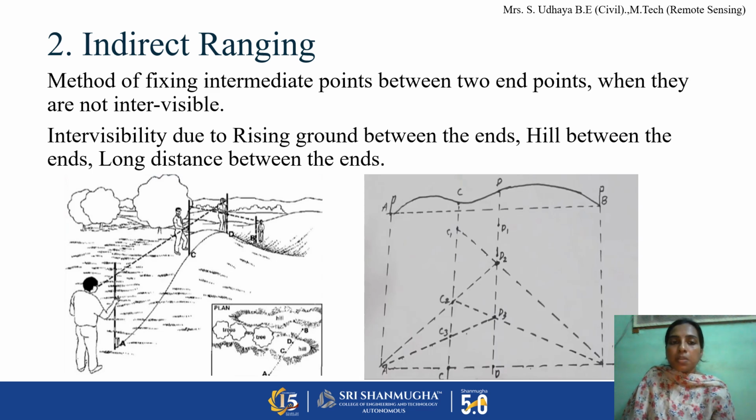It is the turn of the person standing at C. He guides the person standing at D to come in line with A and B, to position D1, making a straight line A, D1, B. This direction is guided by the person standing at C. The position D1 is made by the person standing at D, who moved in between A and B to make the line AD1B.